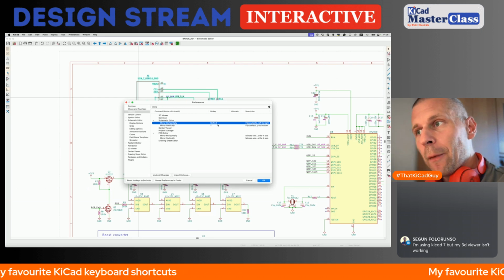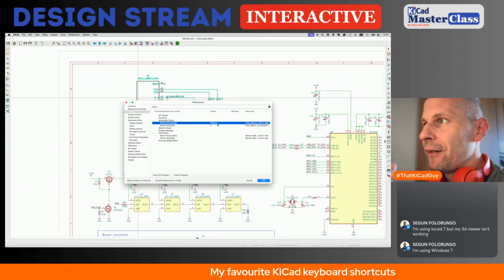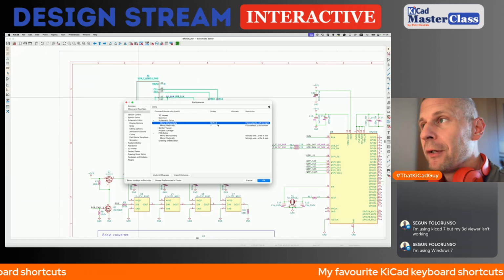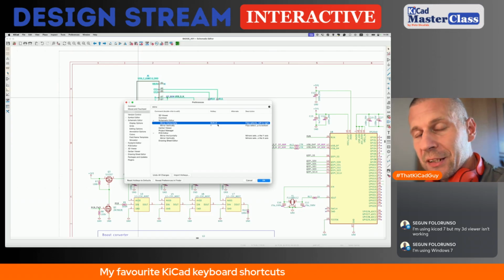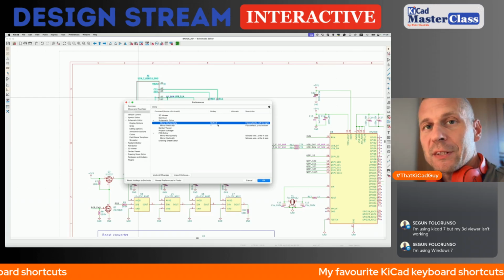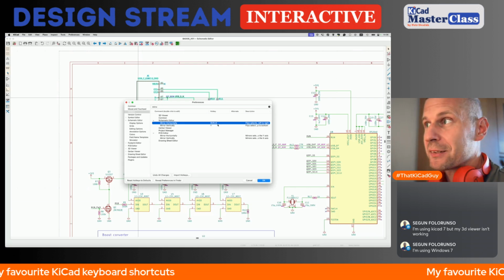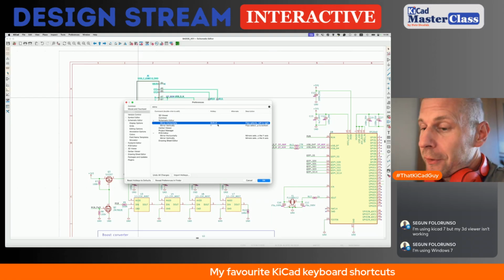I accidentally mirrored the symbol, and when the symbol is, for instance, a diode, which is a better example than a polarized capacitor, there was a serial diode and I accidentally mirrored it. After the next update of the PCB from the schematic, it changed the circuit. So the prototype didn't work. Why? Because I accidentally pressed X. So I redefined it to Shift plus X. I recommend it to you as well. If not, it's up to you.